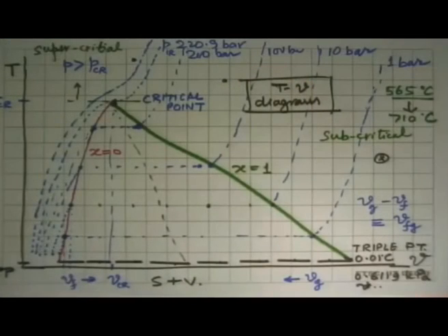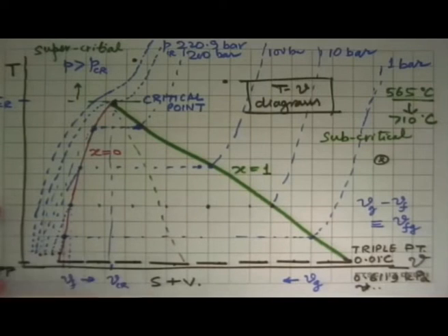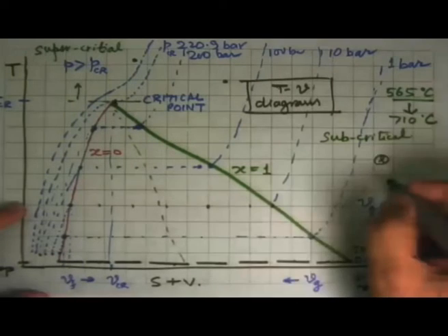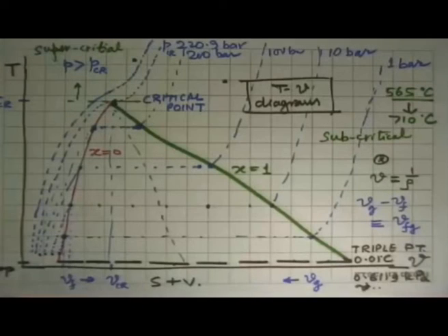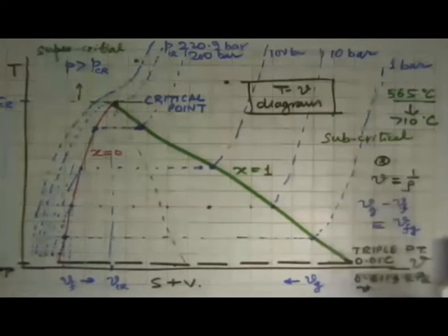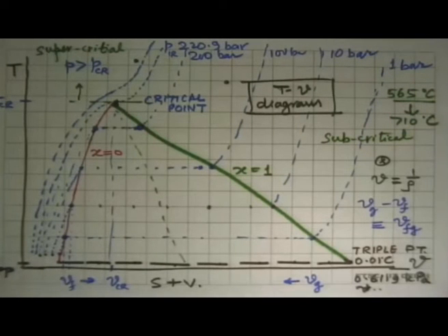Then there is another question. Why does specific volume of liquid decrease as we increase the pressure? Okay. The question is, why are these points going like this when we increase the pressure? Well, if you look at it the other way, by looking at density, when you take water and compress it, its volume goes down. It becomes denser, so density increases, and specific volume is 1 upon density. So when you increase the pressure, the density has increased.